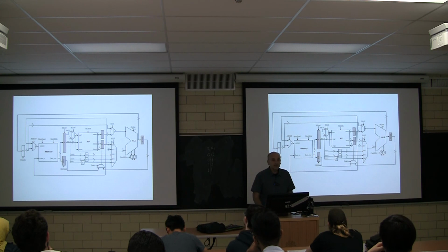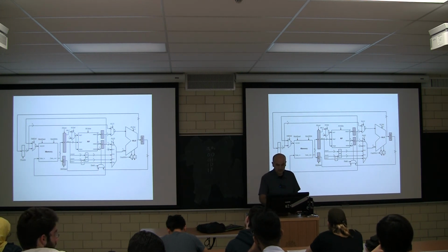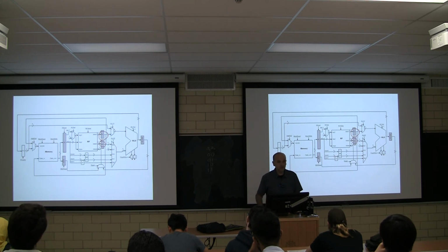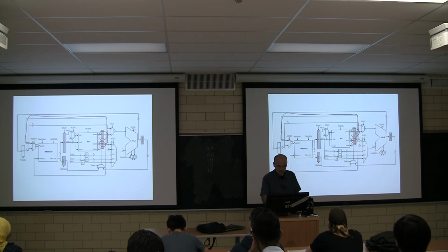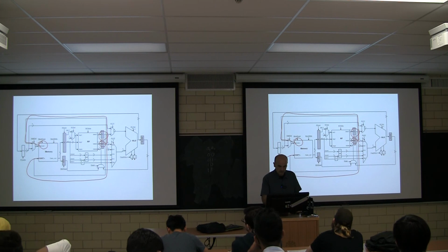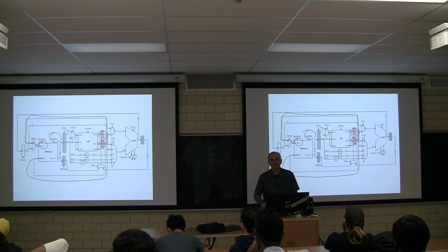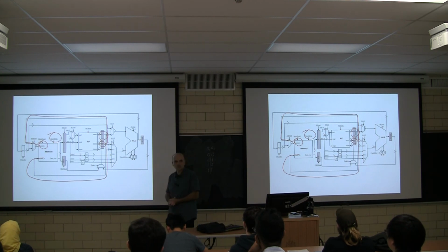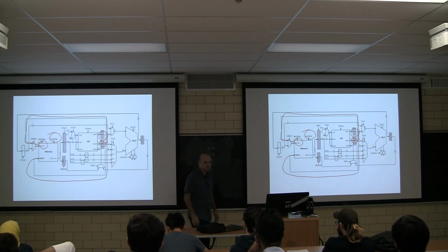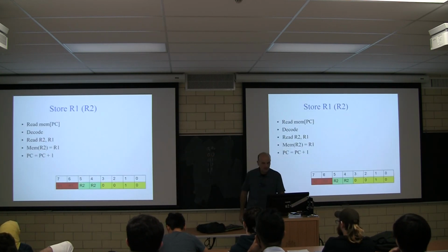Stores are even faster than that. Let's say we're in cycle 3 now, beginning of cycle 3, and we read these 2 registers. Both of them are useful for stores because one is address, the other is data. Again, address goes this way into memory. Data goes this way, and you say memory write. Done. And you're just talking to memory, you can do this in 1 clock cycle. That's store. Fair enough? Okay.